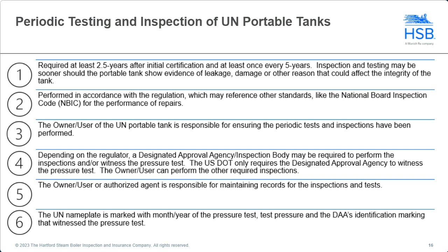You don't have to wait for that time frame. If the tank is showing evidence of leakage, damage, maybe it was in a fire, overheated, or if there's any question of, hey, we don't think it can withstand the pressure or contain the contents, you can do the inspection sooner. And if you're the owner user, probably every time that you fill or discharge, you're looking at it, making sure that it's safe to operate.